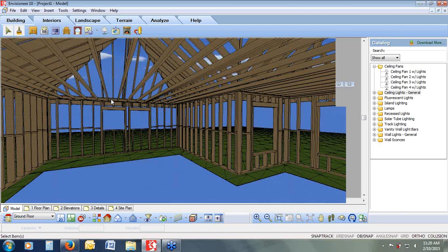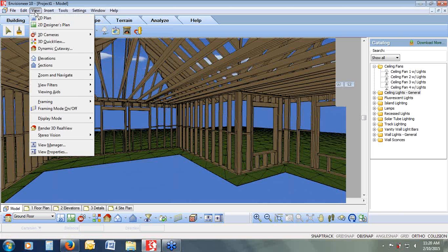There's tables behind all of it so that you can tell it that when you're framing a home, all of your exterior walls are always going to have a 2 by 10 header over all of the openings. Or you can tell it that up to an 8-foot opening, use 2 by 8s, and then up to your next span, maybe to 12 feet, use 12-inch boards. You can do that through the span table.